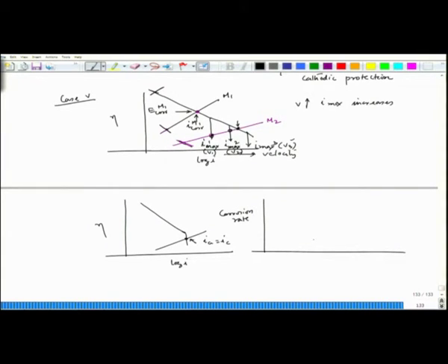In case of metal 1, whether it is V1, V2 or V3 does not matter, because it is cutting all the time on the activation polarization part of that cathodic polarization line. So, its corrosion rate with velocity will be constant, whether it is V1, V2 or V3. All the time it is the same point, same corrosion rate, or I core.